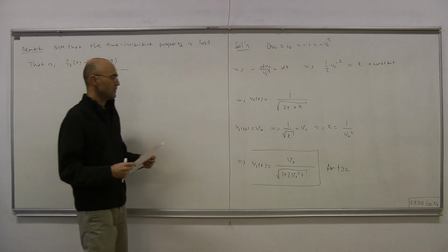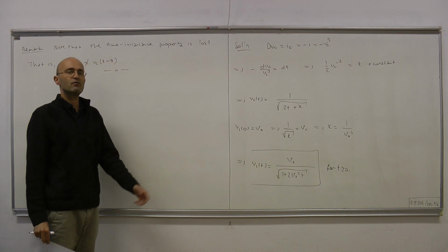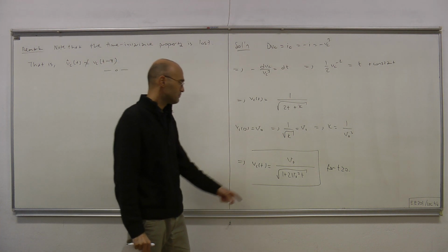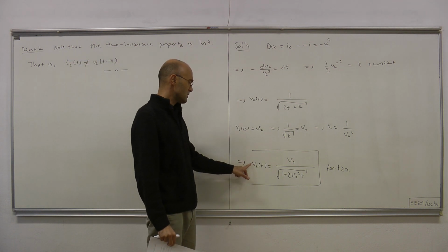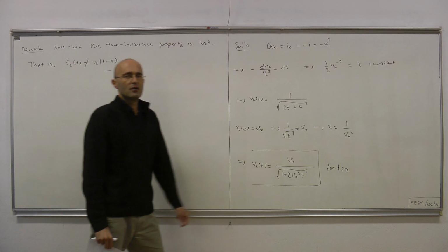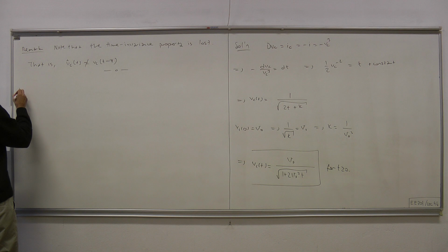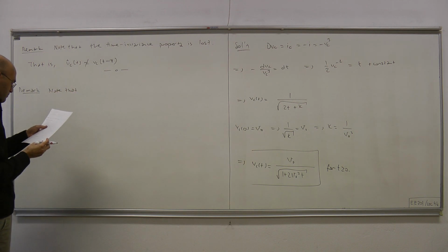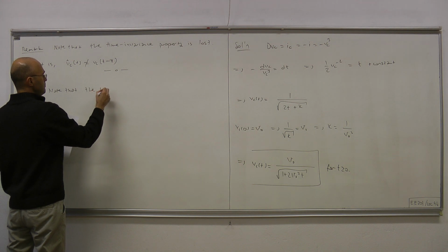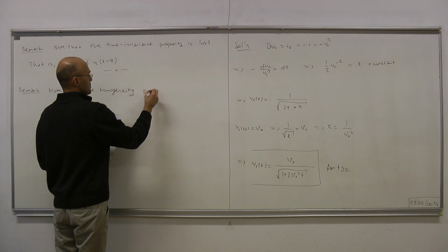Now, we started the circuit from initial condition V0. If you start from a scaled version of the initial condition, lambda times V0, for an LTI circuit, what we expect is lambda times VC t. But for a nonlinear circuit, that's not the case. So let's put that down as our second remark. Note that this time the homogeneity property is lost.